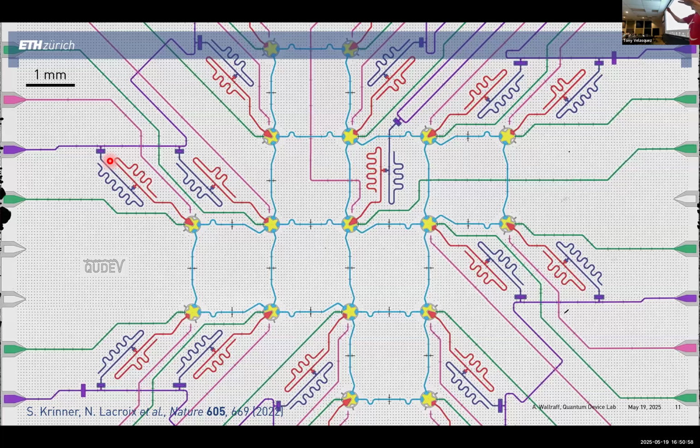And that's maybe something that Daniel had talked about: say you have a detection bandwidth of a gigahertz or so, then for a single detection line, you would space out your readout resonators at a spacing of maybe 100 or 200 megahertz in frequency space. And then your control electronics can target these readout resonators at around, say, 4 to 5 gigahertz, or maybe 7 to 8 gigahertz, spaced out by 200 megahertz from each other. That allows you to frequency division multiplex and address the readout resonators individually.